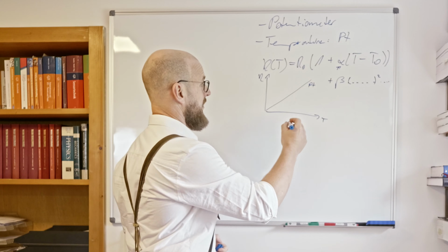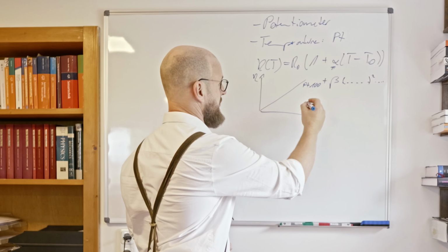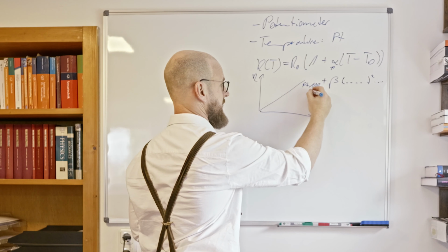Talking about that, often you read something like PT100 or something like that. That 100 corresponds to our base resistance, which would be 100 ohms in this case. And out there are also PT1000s, but there are also other temperature sensors like nickel or chrome sensors, which just have another type of material, therefore have other constants and need another treatment.